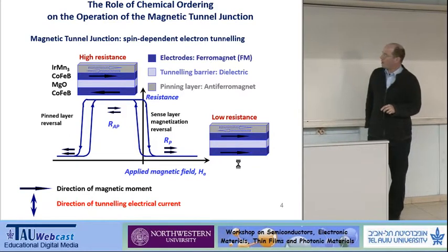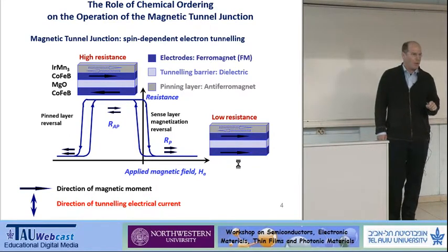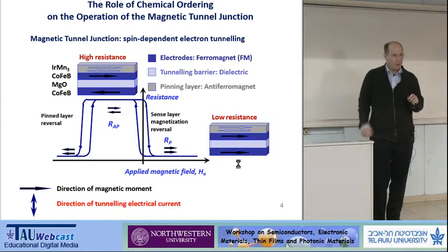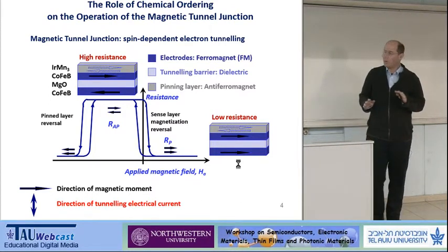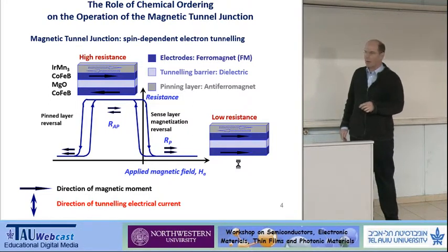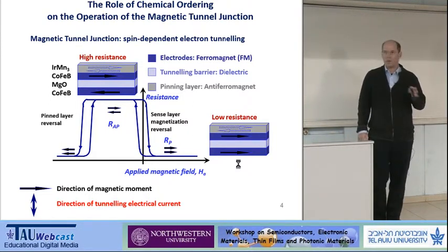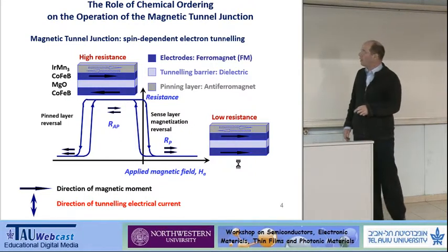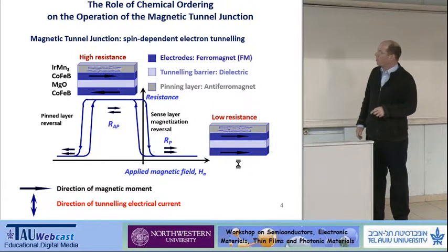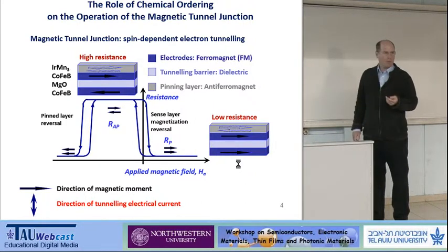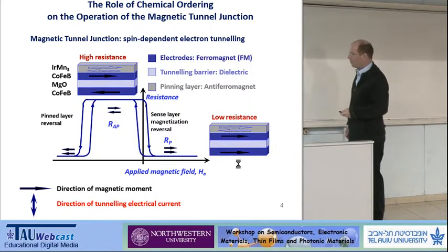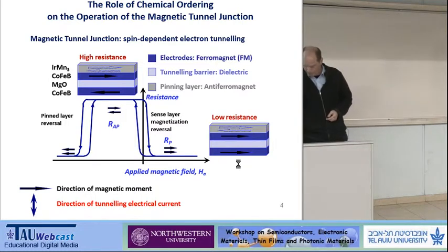And the choice of epitaxial magnesium oxide is not coincidental. It functions as a spin filter. It turns out that due to symmetry matching between the magnesium oxide and the ferromagnetic electrode, there are certain Bloch states it allows to transmit, certain ones it doesn't allow. So this enhances very significantly this effect, which can be, the change in resistance can be many hundreds of percent, even in some cases 1,000%, a very, very strong effect, significantly stronger than the GMR effect, giant magnetoresistance, that at the time received the Nobel Prize in 2007.